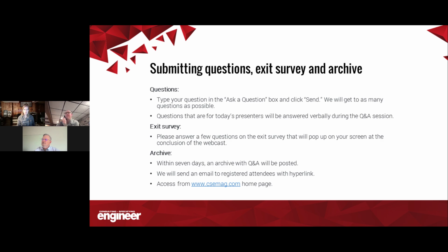All right, this is kind of a hot topic, Rich. Here's another question about this, a related question. We encounter AHJs who mistake the EPS and EPSS and require rated rooms for the EPSS. Have you had similar experiences, and how do you overcome this?